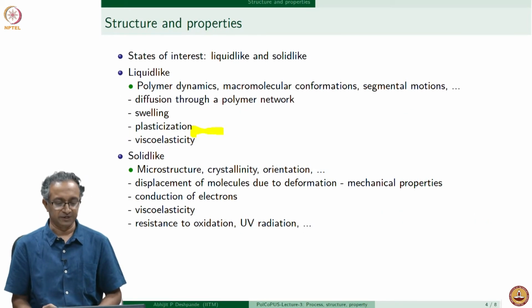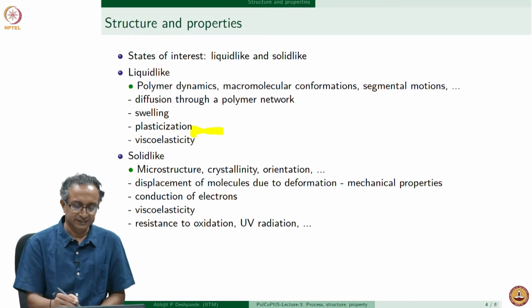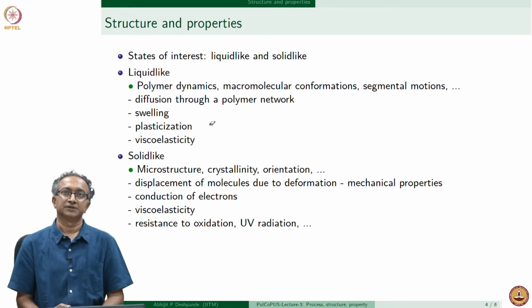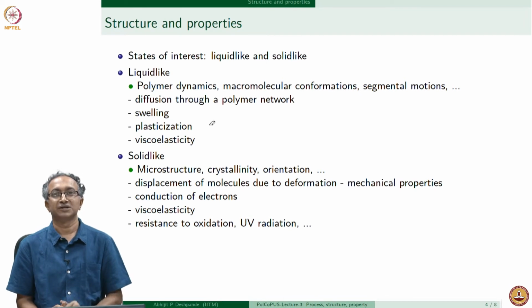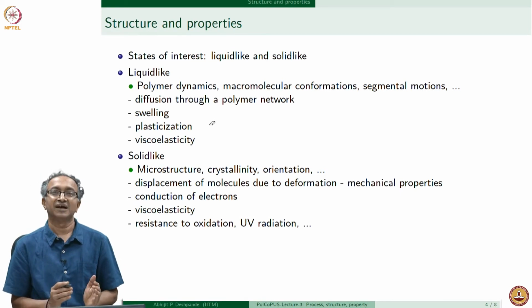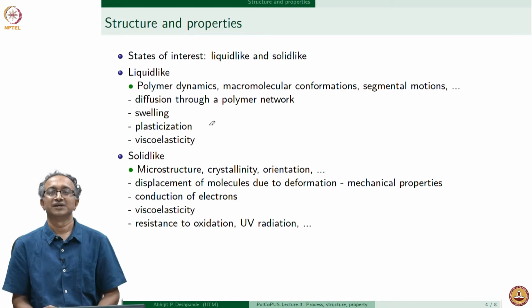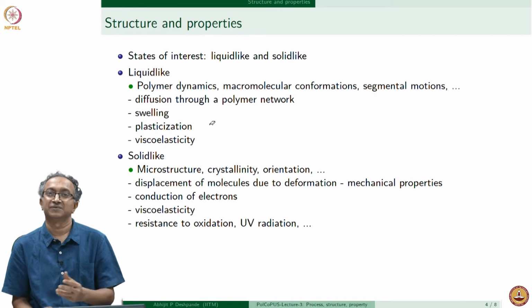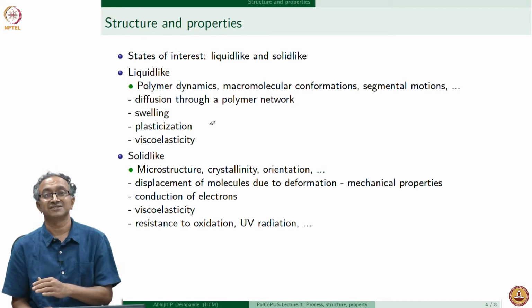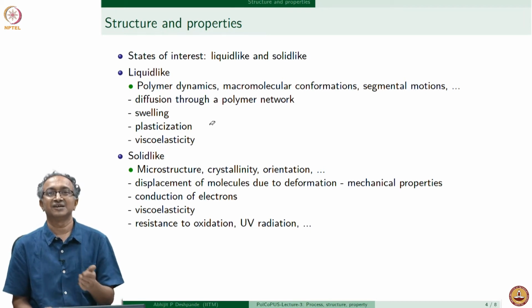What about structure and properties? In case of polymers, basically there are two sets of states which are most important. And one important feature you can notice here is I am not calling them liquid and solid. I am calling them liquid-like and solid-like. And this is something which we will have to continuously learn during the course, that we will have solid polymers which will have some liquid-like features, and we will have a melt of a polymer or a solution of a polymer which will have some solid-like features. So that's why rather than calling them solid and liquid, we will say they are more solid-like and more liquid-like.